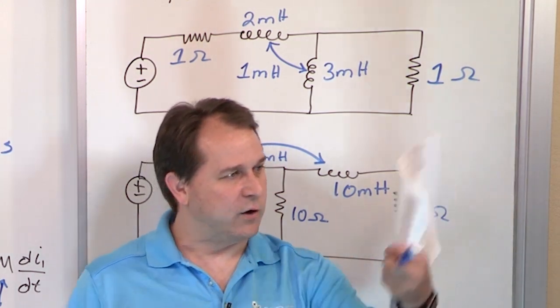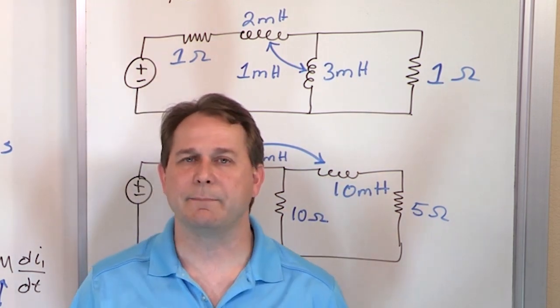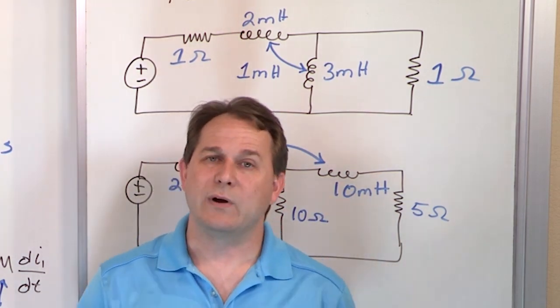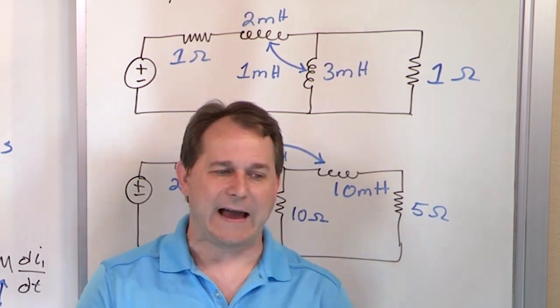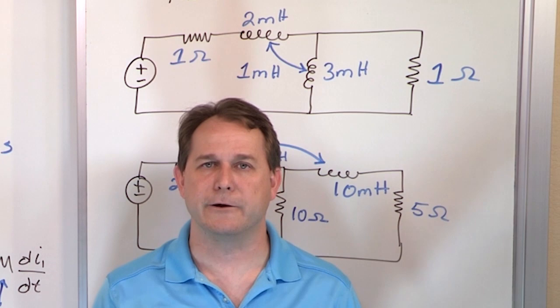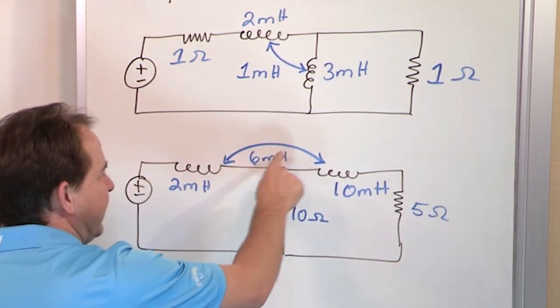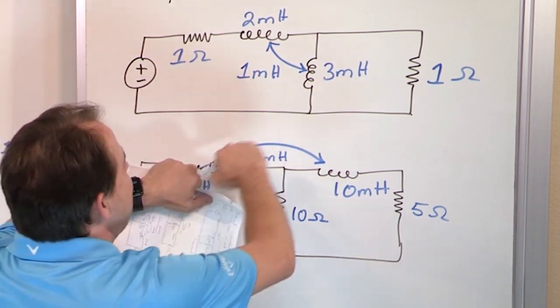So they have the antenna thing going here, like this part of the circuit, and I have some other inductor that's part of some other amplifier circuit over somewhere else. But when I actually physically build the device, I just happen to put those two together just because it fits in the case a little bit better. Maybe if I put the coils kind of close together. So even though they're drawn like this on paper, it doesn't mean that the coil has to be far away.